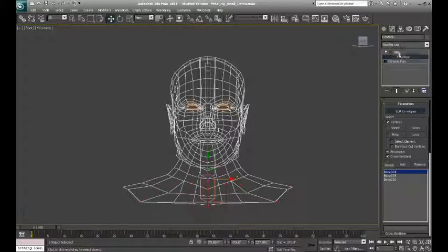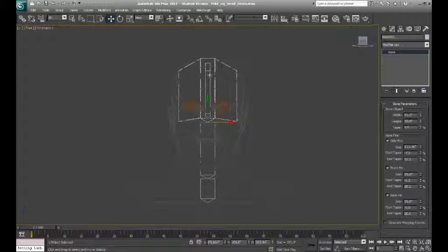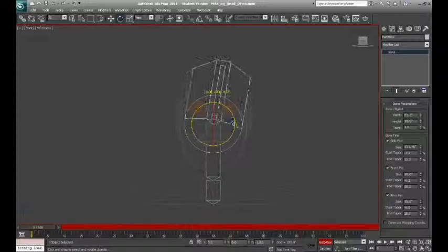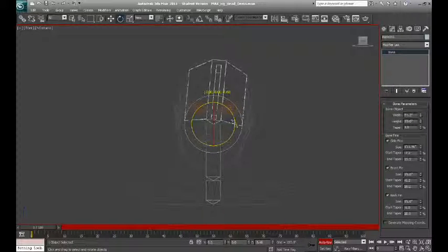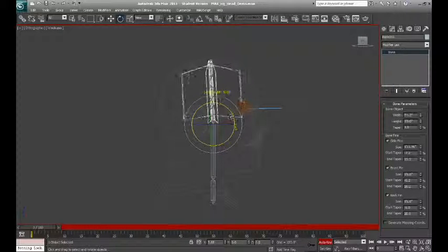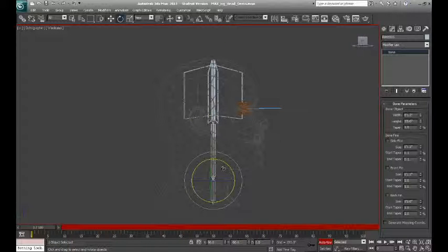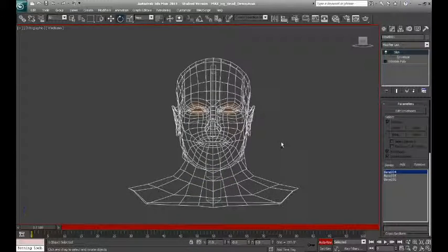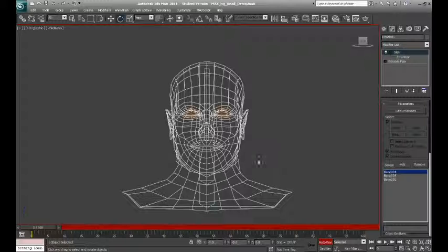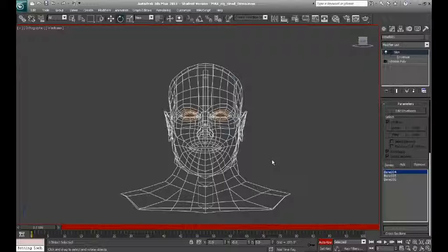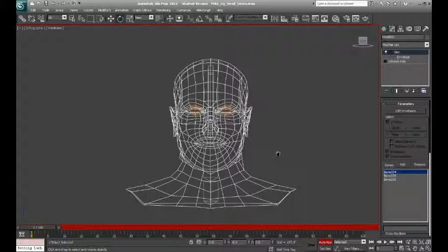And now that you have that in place, what you can do is select your bones, rotate those, and as you can see, those skin weights are going to need to be adjusted, but your bones are in place and you have your skin working. So I'll go ahead and adjust your weights accordingly as per previous tutorial. You'll be able to modify your skin weights. That's also available to you in the demo videotapes.